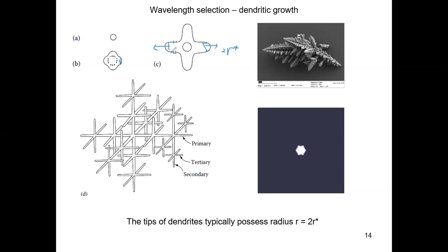So you will see some development of a secondary bump from here and here. Okay, I'm sorry, this is not a good drawing, but basically you can see, right? And then it begins to grow. Roughly, the secondary bump begins to grow and selects the same wavelength, the same size or width as this. And then as this further grows, you begin to develop the ternary. So eventually this is going to allow you to grow into a very complex fractal object in 3 dimensions that is quite characteristic of the initial solid formed during the solidification processes.